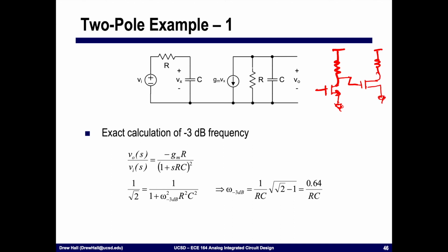And what I would find is that the impedance looking into this one was C, the impedance looking into this one was C, and if I continue this on, all of these amplifiers have an output impedance of R and an input impedance of R, and additionally, they also have input and output capacitances of C. Okay? And so if I am simply cascading amplifiers, this case can actually happen quite frequently.